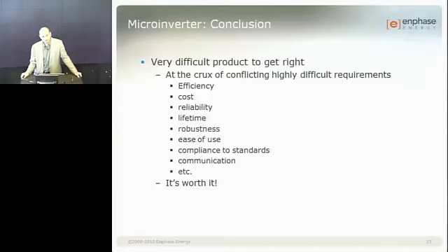The other question is, when you think about a solar farm, when you think about using microinverters, one of the things you think is that you can't eliminate the effect of shading. Sure. So in terms of a big solar farm, it doesn't really happen. So what's the benefit? The benefit there is not, I mean, that's not the way you market your product in a solar farm. In a solar farm, you market your product by the fact that if the inverter goes bad, you don't go down